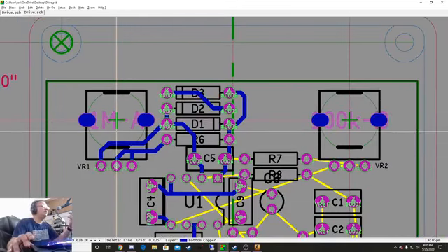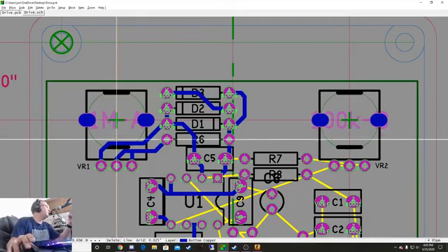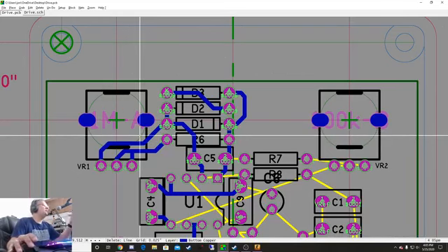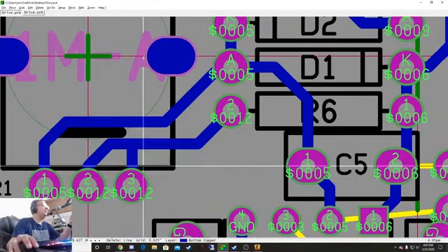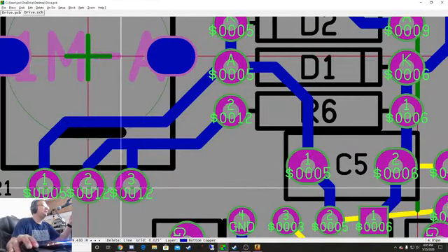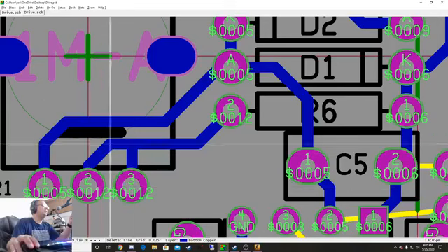Right now I'm looking at the circuit board from the top view, so I'm looking down at the top of the board. Sometimes I lay out a circuit board upside down. And if I forget that I'm doing it upside down, then I might make the pot work counterclockwise by accident. One way you can fix that when you're doing your prototypes is you have the traces not meet underneath here. Instead, they go on the outside.